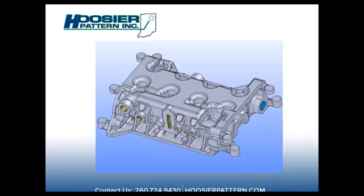The printed molds allow for you to gate and riser rather creatively to get most of your foundry solidification issues resolved. You don't have to worry so much about getting the pattern out of the mold. Your main concern is how do you get the metal into your mold. This is a real breakthrough for the foundry.